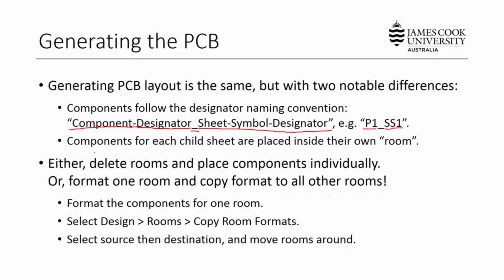Another thing to be concerned with is that all of your components for each child sheet are placed inside of their own room. So there are some crafty things you can do with rooms, and I'll show you how to use them in your PCB layout. There are typically two things you want to do: either delete the rooms entirely or place the components individually.